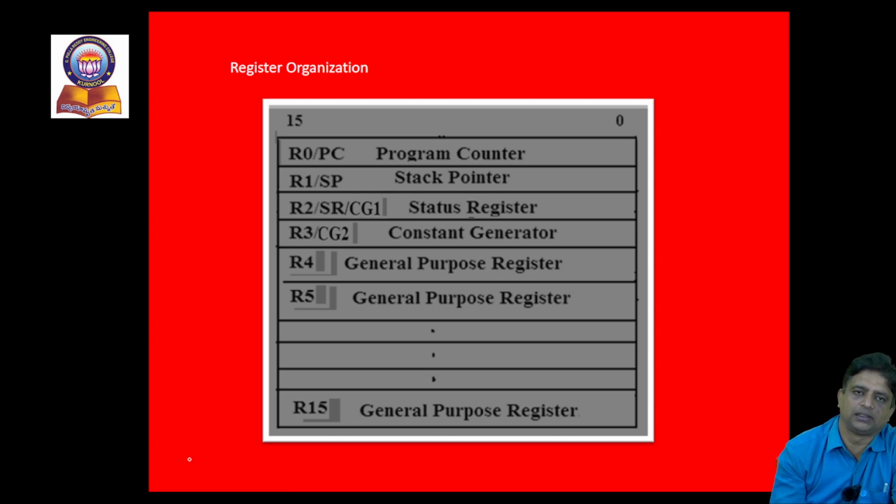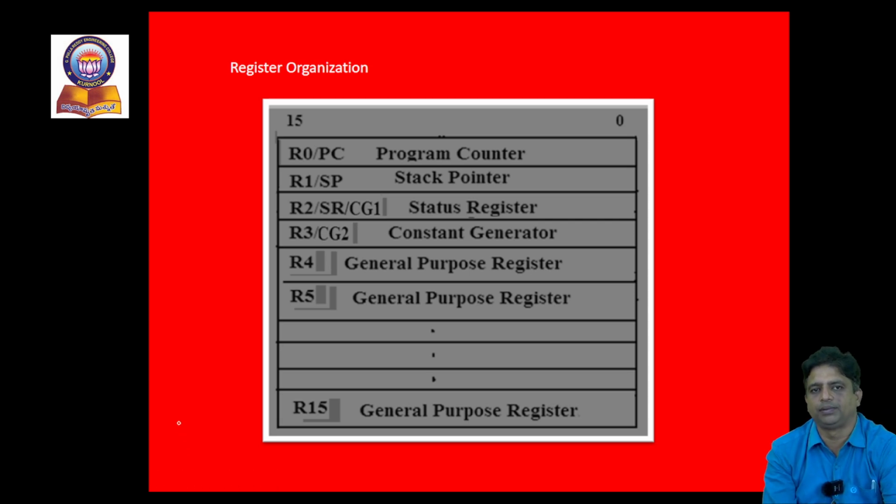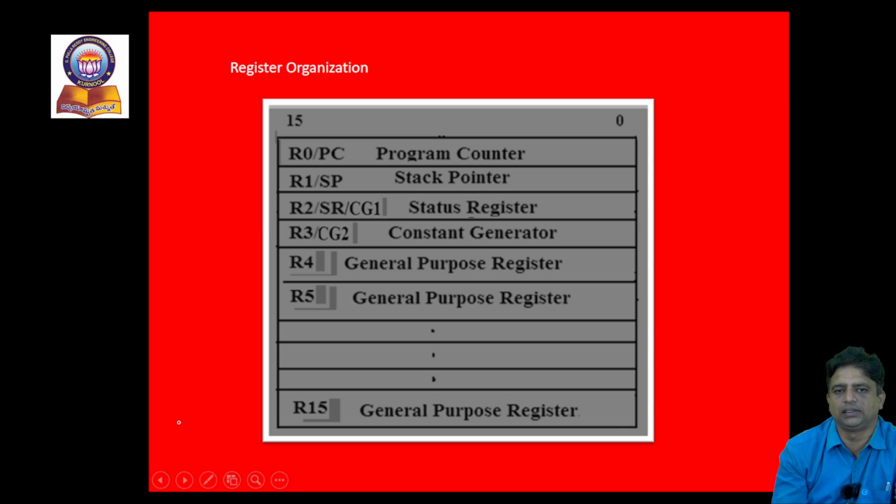Out of this processor registers, some registers can also be used for multiple operations. As mentioned in the list, each register with respect to its data and address capacity will be 16-bit of size. So the register count is also mentioned as R0 to R15. Totally 16 general purpose registers are being present, out of which few registers are parallelly or multiplexed in another format to be used for addressing purpose also.